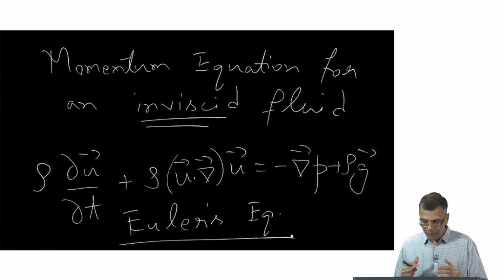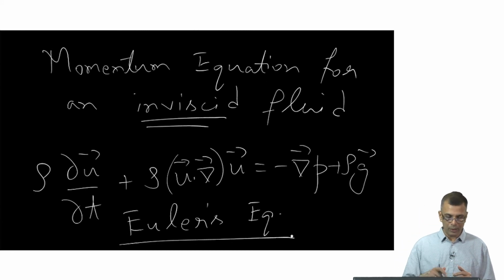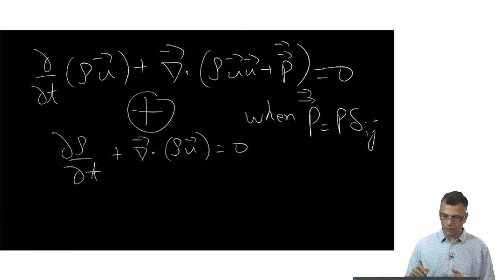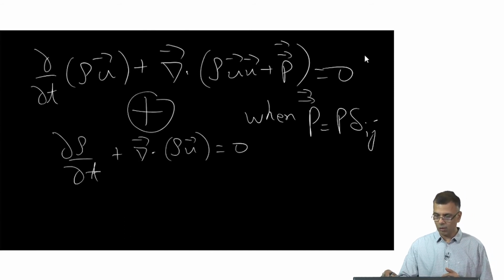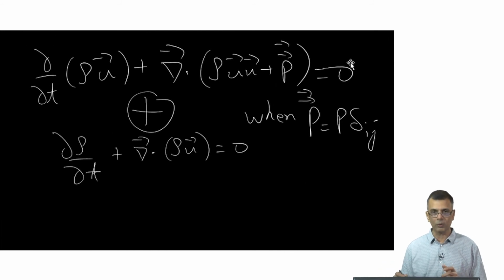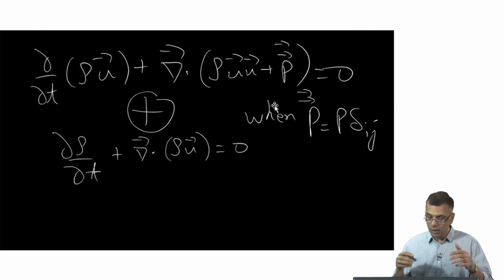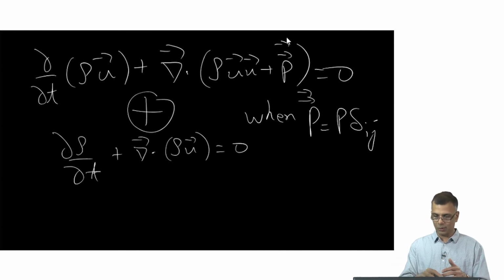So this is the momentum equation for an inviscid fluid. In general, the full equation is true for any situation. You can include body forces here if you wish, but as such, this includes a situation where viscosity is included. So, we've already introduced what's called the Navier-Stokes equation. We will discuss it separately in a minute. But this is how the Navier-Stokes equation, which includes viscosity, arises.